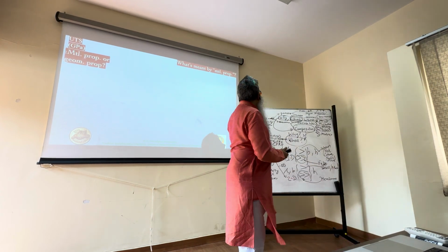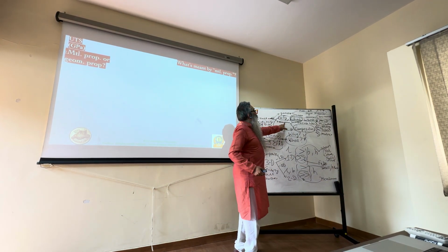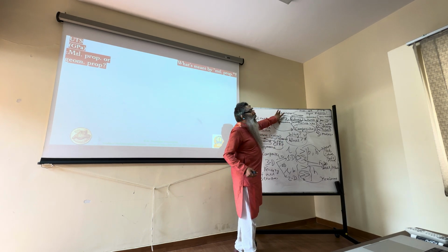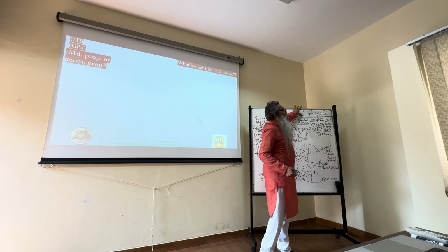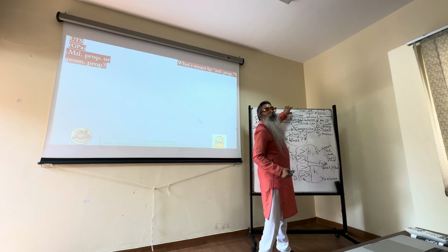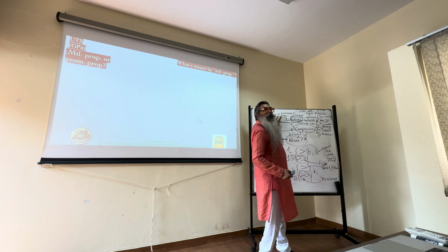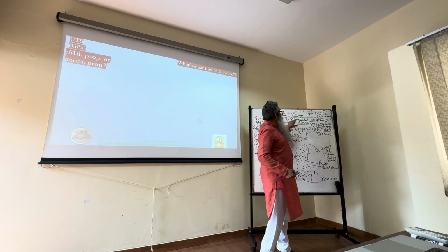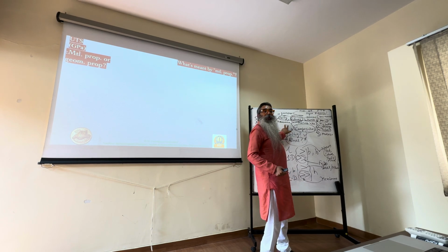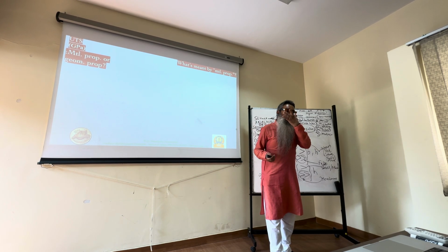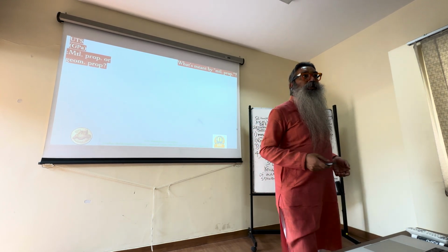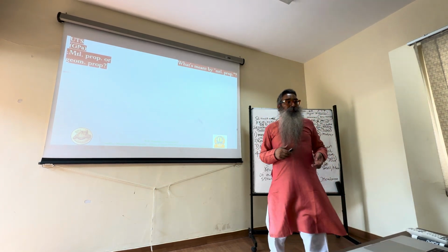Right? Because that's what we said when we said structures. We said it's made out of two aspects, the geometry and the material, and the geometry is made out of shape and size. So shape and size are entirely geometric features. They are not material features. So if I keep the material the same and change only the shape or size, obviously the material should not change. And if the material doesn't change, the material property should not change. Therefore, UTS should not change if it's a material property. That's essentially what we are trying to understand out of this, right?